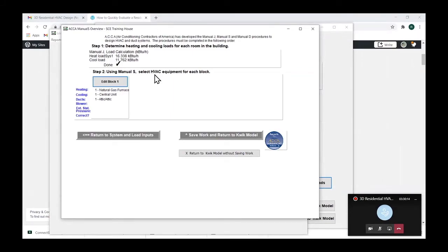And I will also throw this in. Reducing airflow not only reduces your capacity, it also reduces your efficiency. It reduces your SEER rating on your air conditioner when you reduce airflow. So sizing ducts properly, knowing how to size your ducts to ensure good airflow, is important to sizing your air conditioner. So that's a big deal of Manual S.